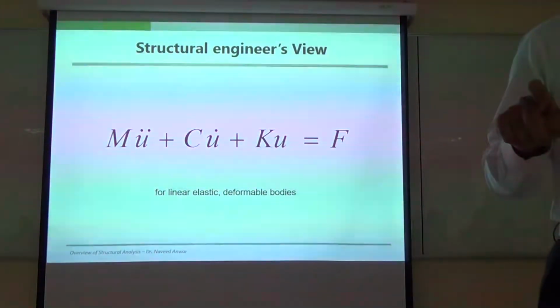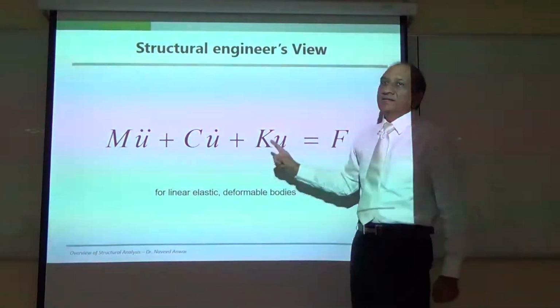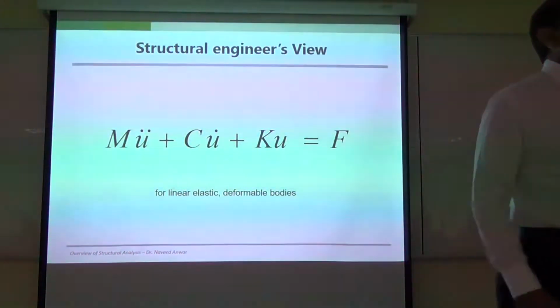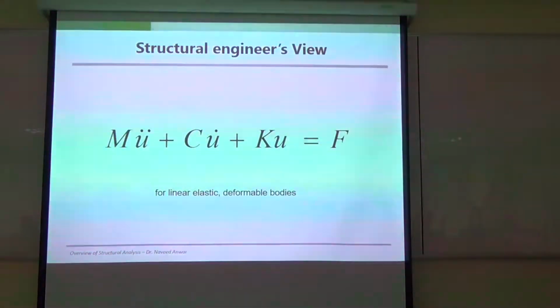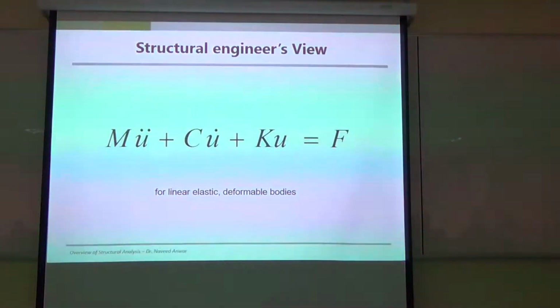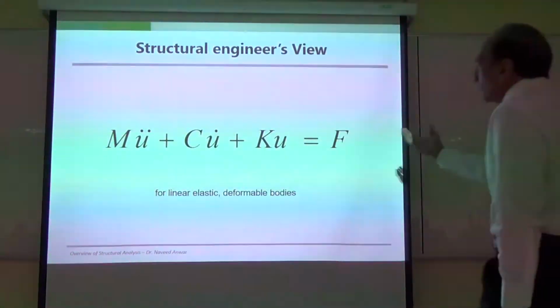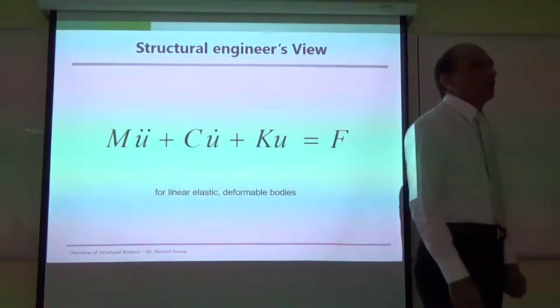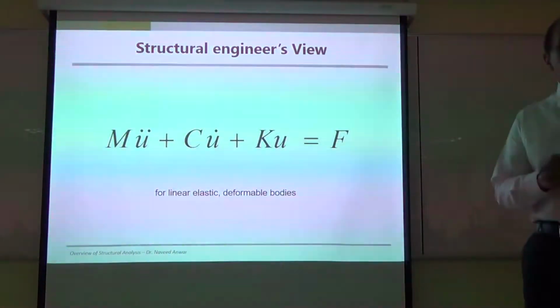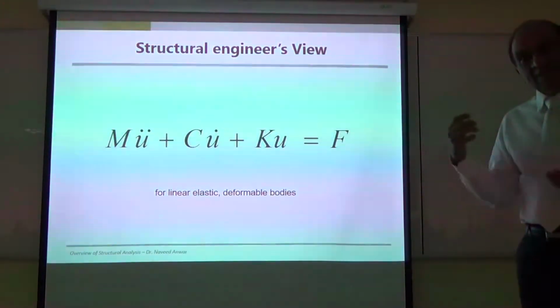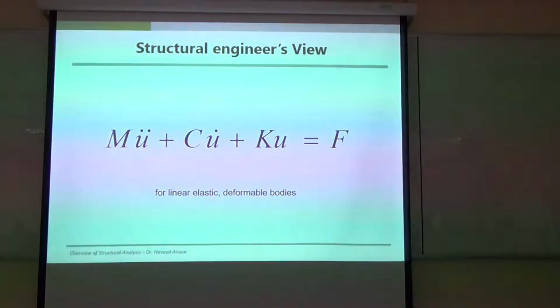Nonlinearity, damage. This is still assuming that the structure is infinitely strong to resist every displacement, every force generated on the structure. So it does not include nonlinearity. It is still applicable to linear systems. So it's a linear dynamic equation. The first one was the linear static equation. This one is the linear dynamic equation. Nonlinearity is still missing because this is still assuming that the structure can continue to deform infinitely, never break, never fail, never collapse. So it's incomplete still, right? Never degrade.